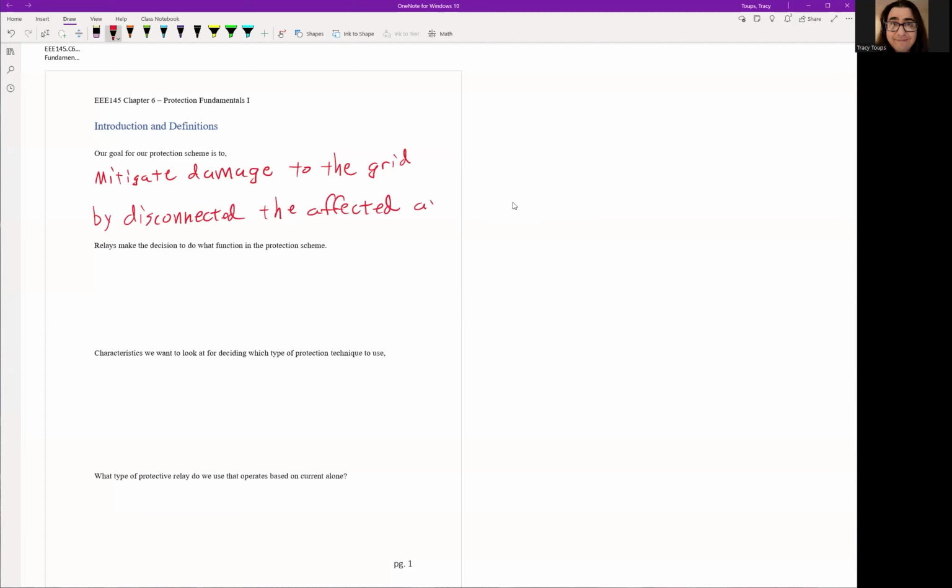Whatever the problematic area is, basically where the fault is, you want to just disconnect it from the rest of the system, right? That way the system can keep running, it's stable. We disconnect the faulty system so that public safety is better, and we can go and repair it, right? Because at the end of the day, we won't bring it back into service.